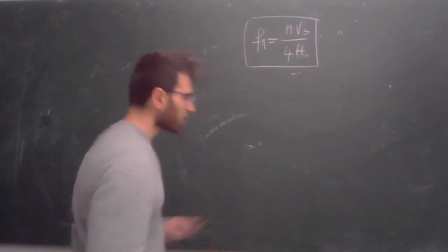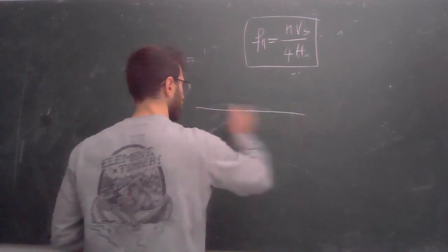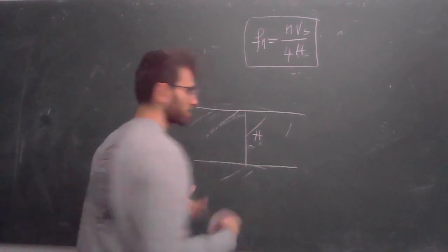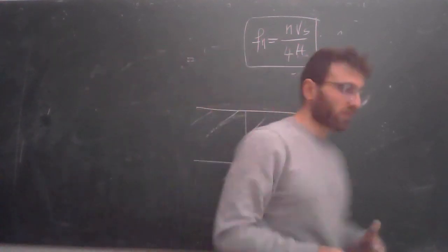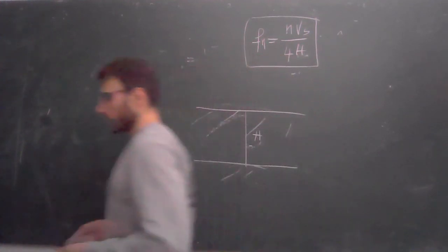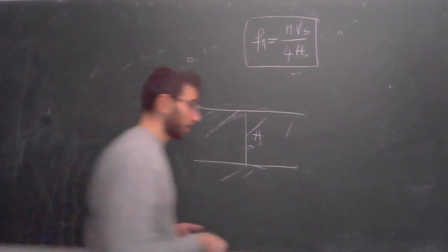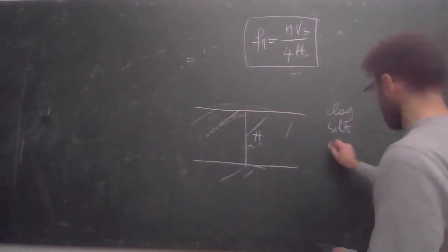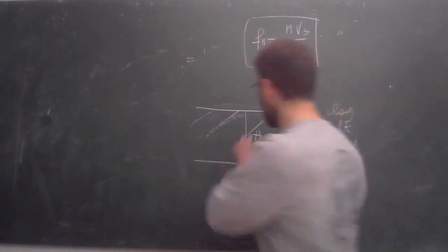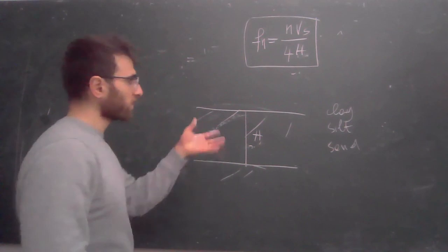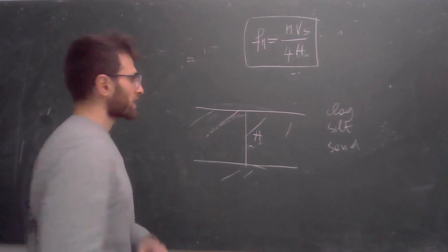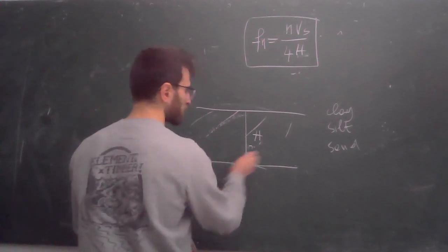I don't know if you see the importance of this expression. If you have to build a house, there is always the soil, the bedrock, and the deposit. This is the deposit. We do not build over the bedrock generally. There are many deposits of clay, silt, sand. And that deposit can be viewed in seismic engineering in the optics of the wave equation, where shear waves propagate from the bedrock to the surface.